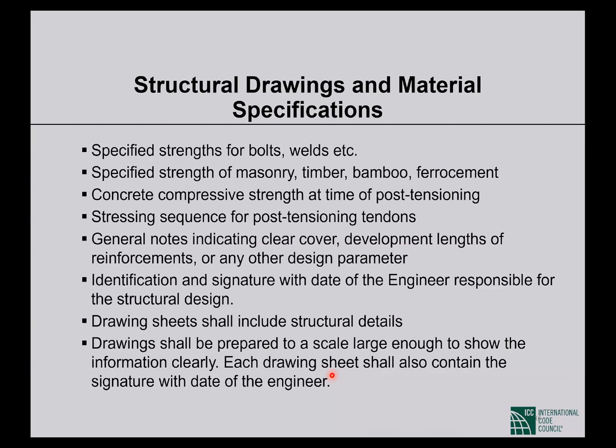Specified strength of masonry, timber, bamboo, ferrocement. Concrete compressive strength at time of post-tensioning. Stressing sequence for post-tensioning tendons. General notes indicating clear cover, development lengths of reinforcement, or any other design parameter. Identification and signature with date of the engineer responsible for the structural design. And then drawing sheets shall include structural details. Drawings shall be prepared to a scale large enough to show the information clearly. Each drawing sheet shall also contain the signature with date of the engineer.